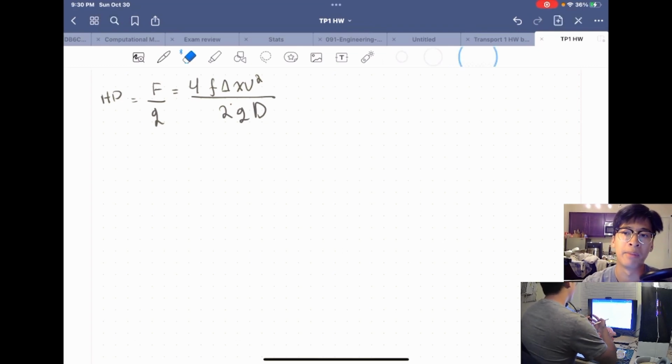In the past, we have been able to guess something that's pretty generous in terms of error, and the solution will still converge. Whereas this time, it's not so true. The root solver has a lot of trouble converging on a solution if we don't provide it a good guess. So we need to do a little bit of handiwork and be a little intelligent about what guess we need to provide for Q, flow rate.